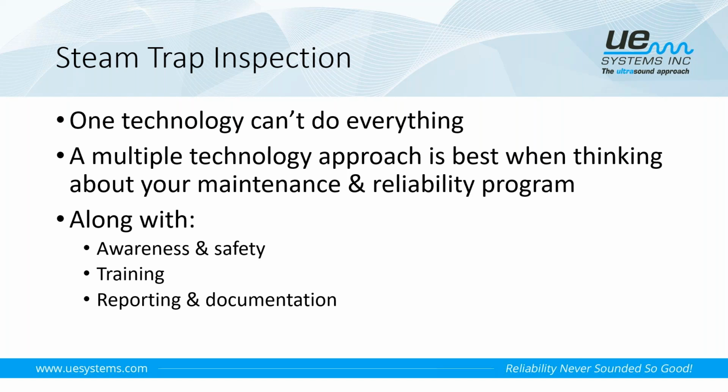So again, combining temperature and ultrasound, similar to the way we talk about using ultrasound and vibration together with mechanical or rotating equipment inspections, and ultrasound and infrared together with an electrical asset condition monitoring program. Again, one technology can't do everything. We certainly don't want to rely on one technology to make a good diagnosis of the health of that asset or that steam trap.